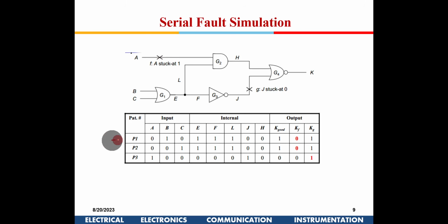So you are giving one test pattern here, right? This is getting generated, and if you are not dropping off that fault, you give the next test pattern. Again the same fault is being detected, this is the fault free output. Okay, and you give the next pattern here, then the next fault is being detected here, right? So if you are doing fault dropping, then this won't be there in the next run.